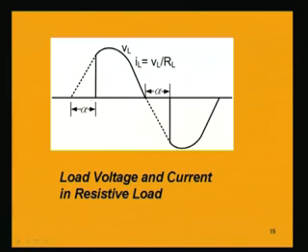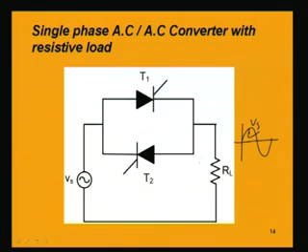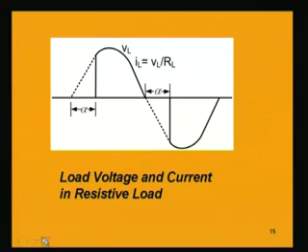because there will be no current flow in the resistance RL. So, till the firing takes place, the voltage across this resistance, which we name VL, the voltage across the load, is 0 till alpha in the positive half cycle, because till this point the thyristor T1 is not firing, and there is no question of firing in the thyristor T2 as well, as it is reverse biased. I mean, the cathode is positive where the anode should be positive, and after this, the thyristor T1 will conduct.